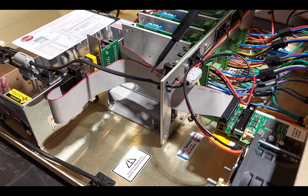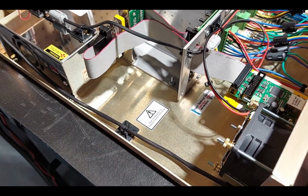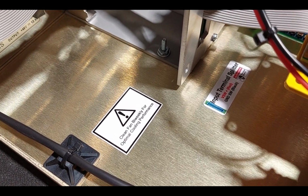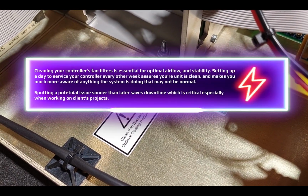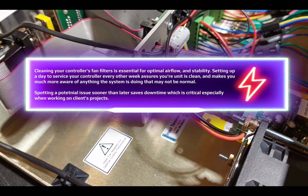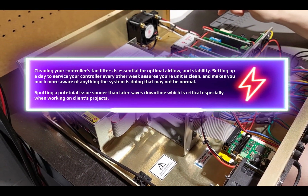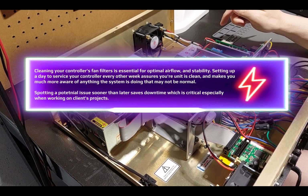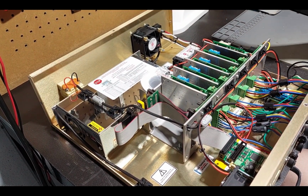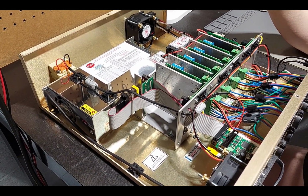We then have our service labels, once again, for our fans, so end users understand that they should be cleaning their system on a regular basis. Number one, it makes them pay attention to it, and you'll find things that may pop up their ugly head over time. But servicing your system over a 2-week period, everybody should do. I don't care if it's only being used an hour a day, 2 hours a day. You should be understanding exactly what you're working with. And that's the best way to do it. If you see something out of place or something just doesn't sound right, that's the easiest way to identify issues.